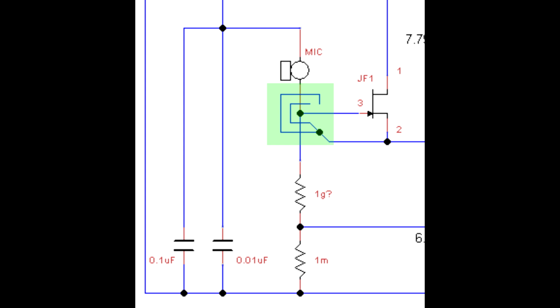So when you do the PC board layout, there are rings around that node to keep any stray capacitance to a particular value. Imagine that's a little capacitor going from that node to someplace else, to the rings of that guard. And it's kind of like a little capacitor. As long as the center of the capacitor and the ring of the capacitor are at the same potential, then there's no problem. And so the way that the circuit works is it makes sure that that ring is at the correct potential. That ring is tied to the source of the JFET, and it makes sure that everything is stable.